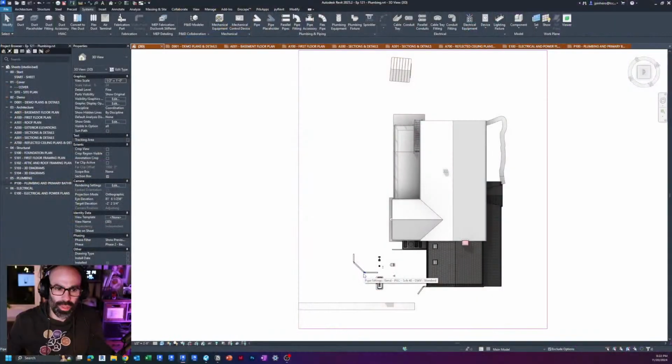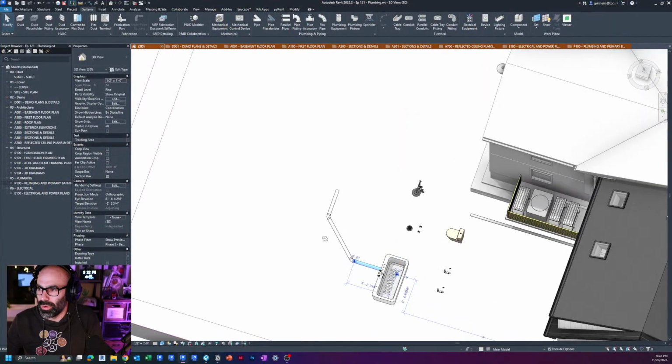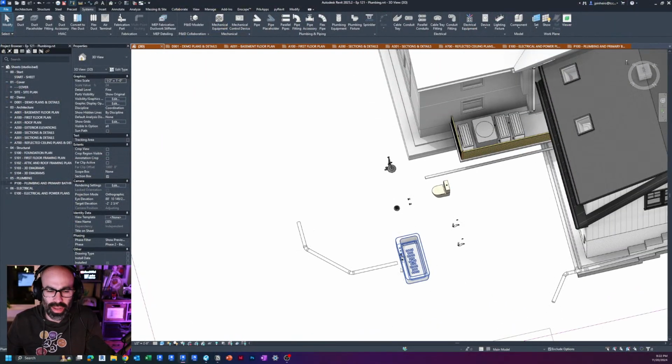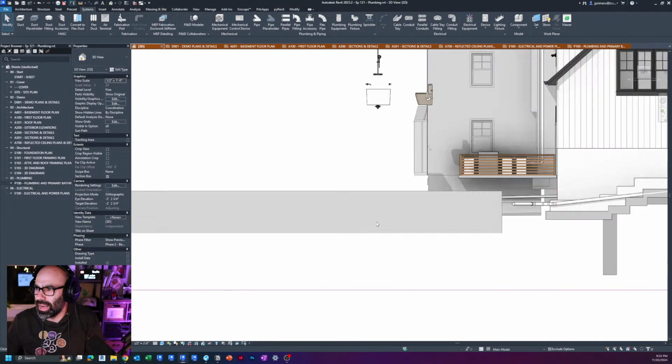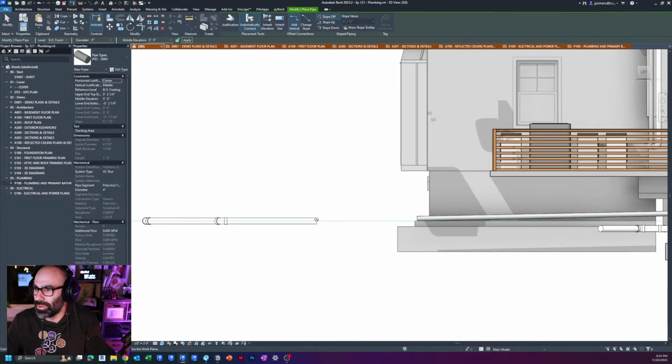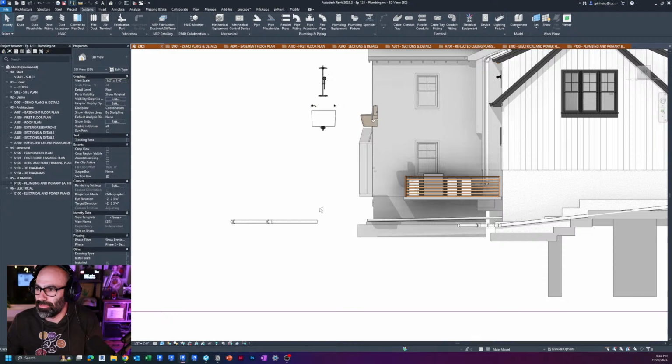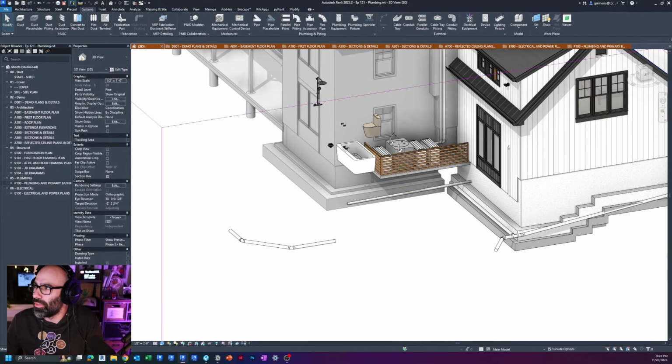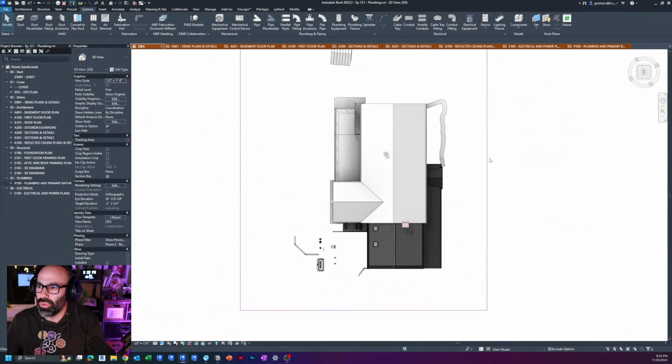Once you have these routing preferences, you saw how easy it was for me to do that, right? I didn't even need to think about it. I can just model, okay? What's nice about plumbing is that, by putting it outside the building, none of my views are going to work at this point in time, but that's okay. So we have A, we have B, and now let's just run one real quick.